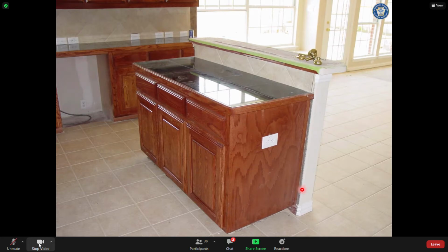And since I don't have that documentation, I'm going to assume that this house was not built for someone that is physically impaired. And the other condition that would allow me to put this receptacle right here below this countertop is if I have no backsplash. Do I have a backsplash here? Everybody shake your head, yes.